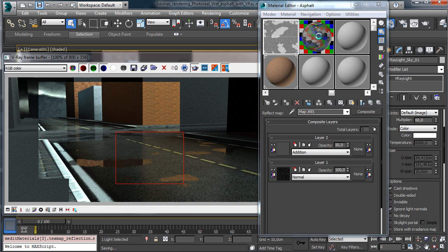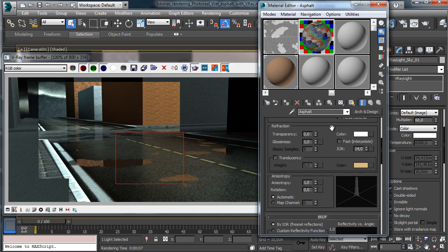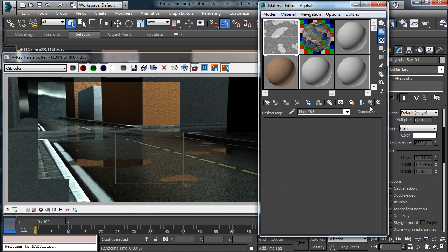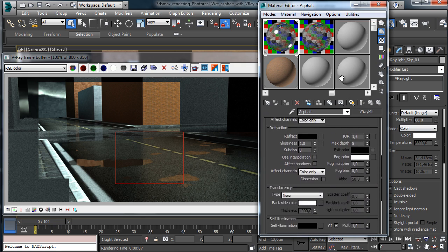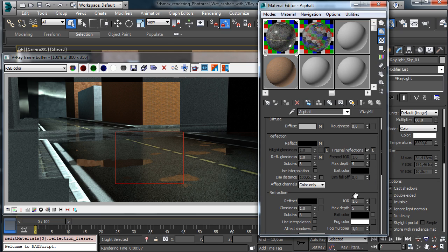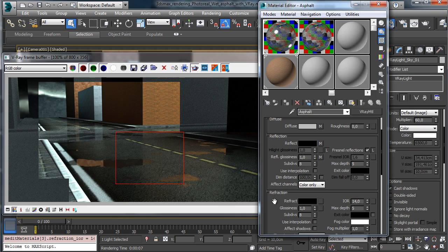So for sure we had in the VRay version of our material a bump mapping. If we go to play with it, but obviously we have also to control the reflection. Okay, we have no Fresnel reflection, and that's nice. We can have maybe a little bit of Fresnel reflection, and we can just maybe play a little bit with the parameters, but I like to see if the reflection is okay. You see, in this way it is taking care about the index of refraction. Let's use an IOR value. Let's use 16 for the subdivision to have a better reflectivity.